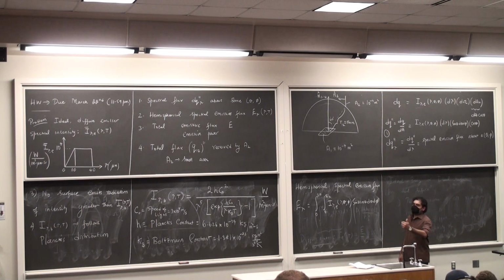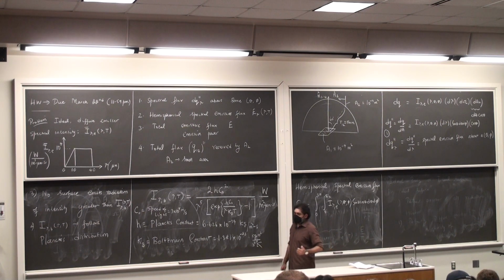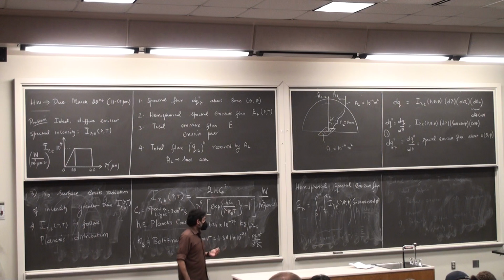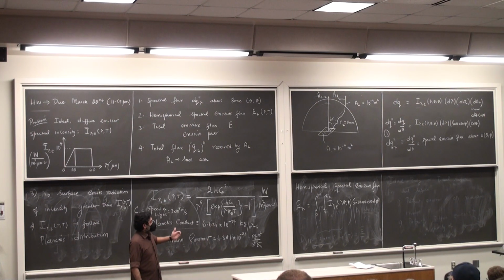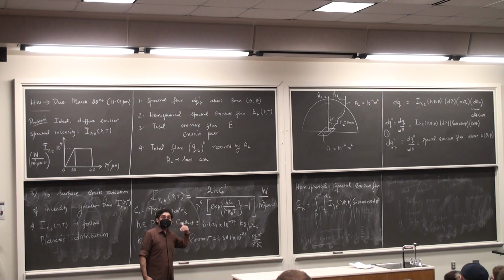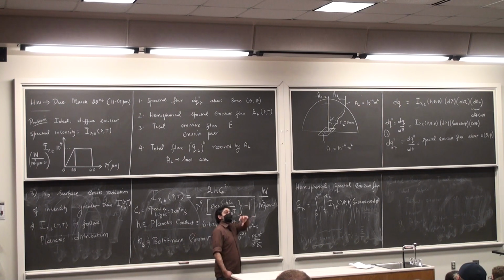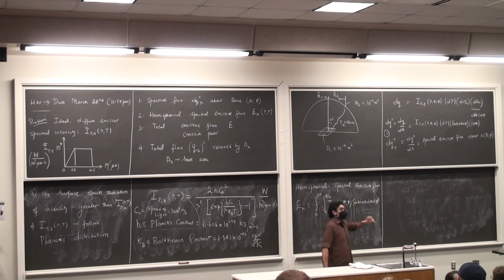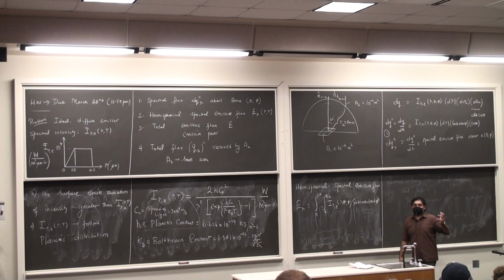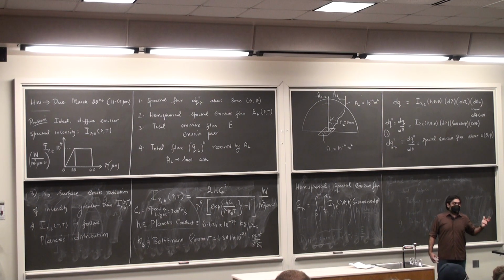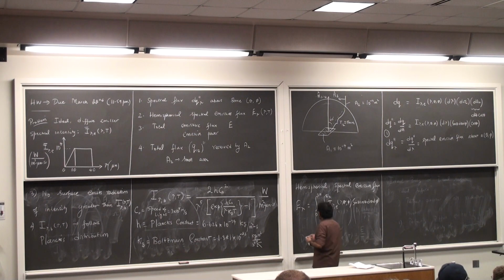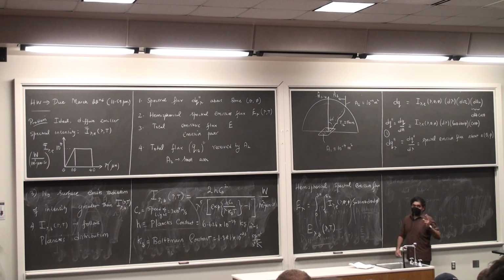And here I lambda comma E is the intensity of radiation. But if I do this for an ideal surface, then what happens is that my ideal surface is a diffuse emitter, which means that I can take this guy out of the integral, and I'm just going to have integral sine theta cos theta d theta d phi, which is equal to pi. So for an ideal surface, E lambda comma B, which is a function of only lambda and temperature, okay? The suffix B represents the fact that this is for an ideal surface or an ideal body.